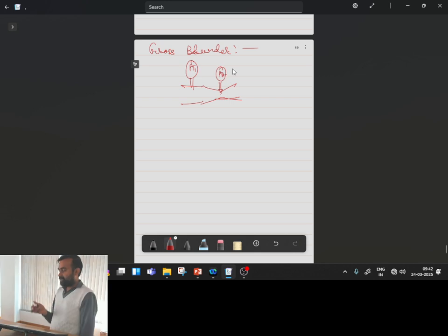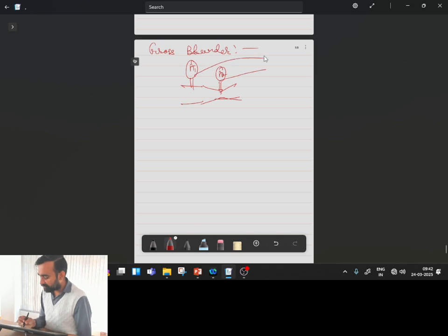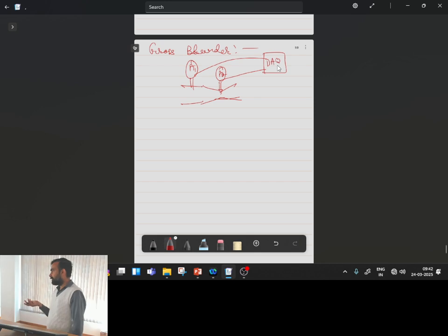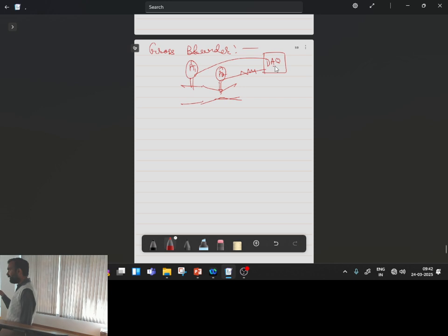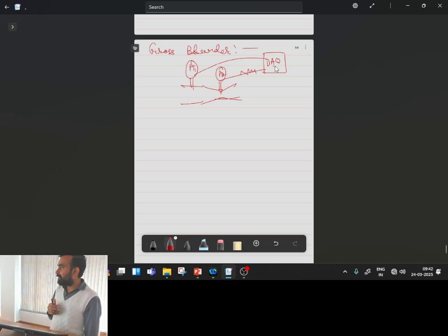Say these pressure transducers are to be connected to some data acquisition system, and you have taken the measurement, and after taking the measurement you found that this cable was not connected to the transducer. So whatever data you get will be significantly, or very, random. This type of mistake, which is because of a major fault while we are doing the experiment, is called gross blunder.